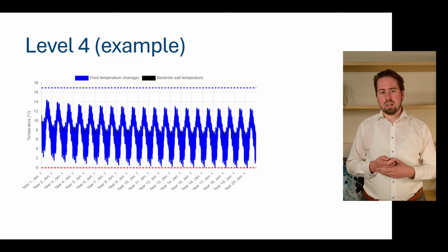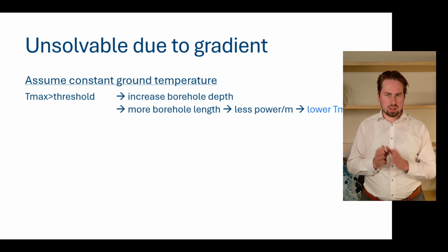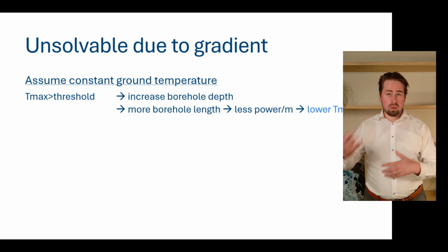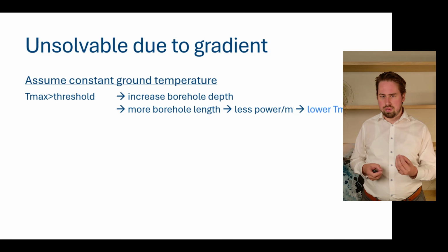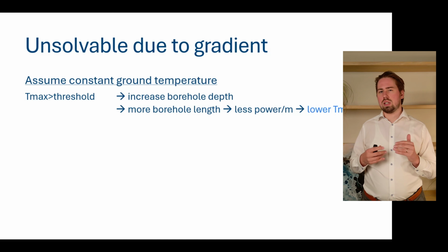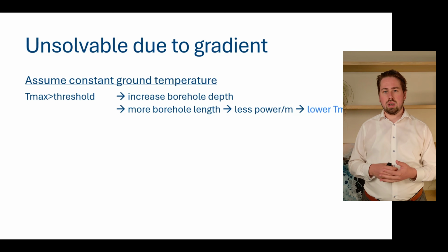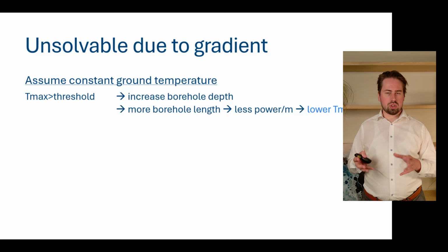Now, before we jump into an example, I want to talk with you about the unsolvable due to gradient error. Because when we're designing with this methodology, sometimes there is no feasible solution. And in order to understand that, we need to remember that GHEtool considers both the maximum and the minimum temperature limits, in contrast to other design software. So consider the case where there is a constant ground temperature.